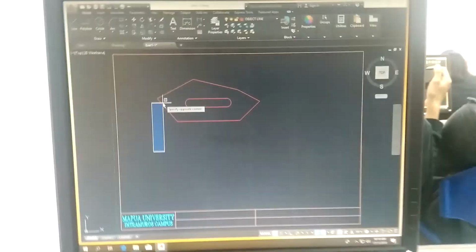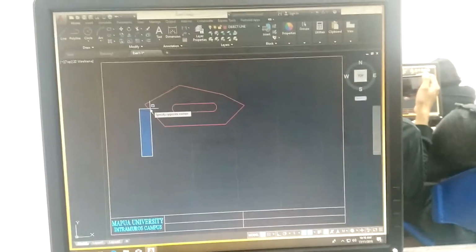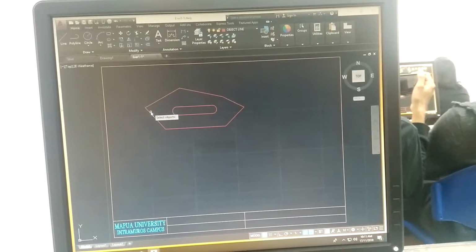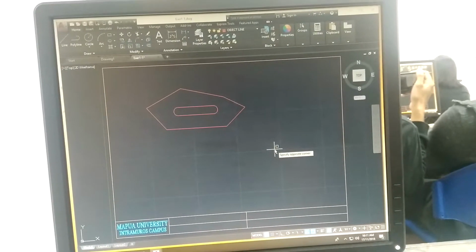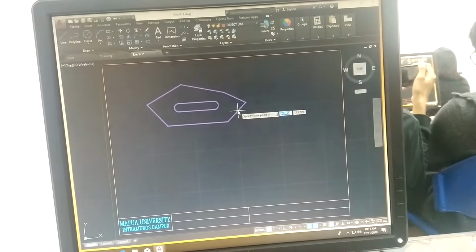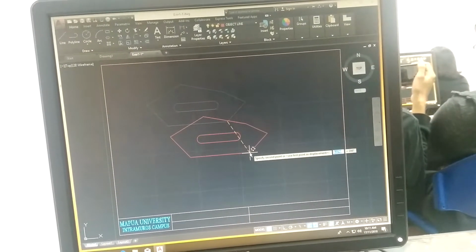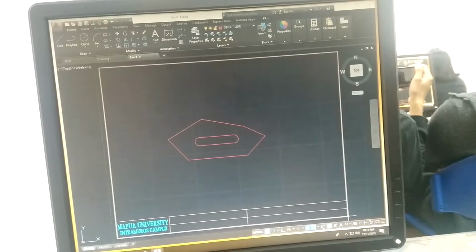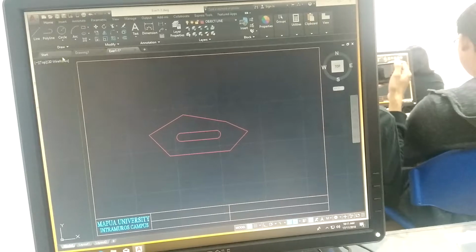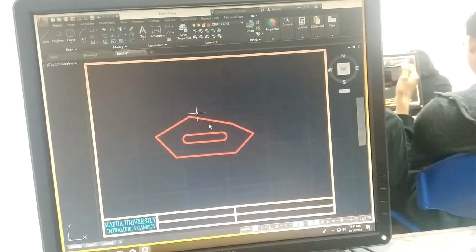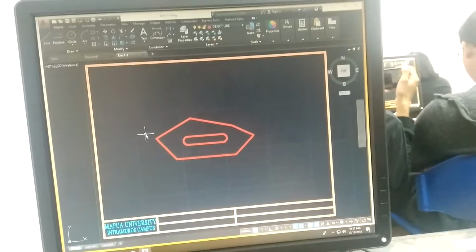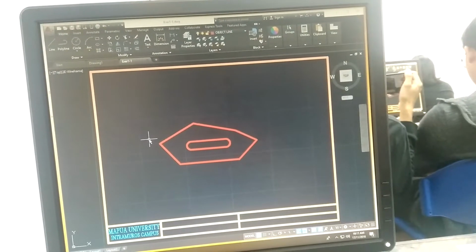This topic will come out in your final practical exam. So I will select all. I will start from the right, going there. Even if not inside, it will be selected. Enter. Check the line weight. Correct. Assuming I'm done, for the final save, you turn on the line weights and save. For example, if you had difficulty, even if not finished, it's okay.